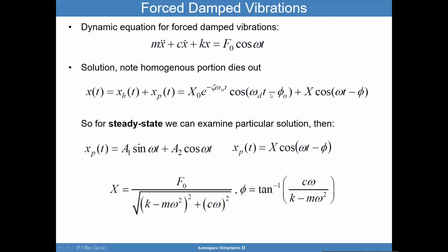And so these terms will disappear, and you will get a steady state motion driven mostly by this term right here. And so an input that's of harmonic nature as a forced vibration input is going to cause, if you have a damped vibration situation, an initial transient solution, part of the solution, plus a part that will not die out, and that's harmonic. And this is the steady state portion.